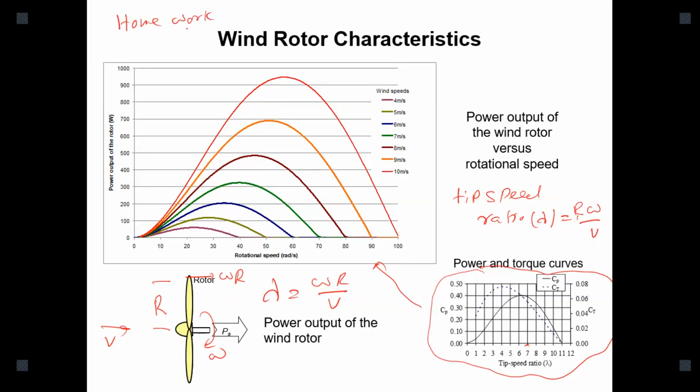Okay, I'll give that homework in the Moodle. However, for the homework, if you know the wind rotor diameter, shall we think our diameter is 126 meters, same as the Mana wind park Vestas wind turbine. If these are the CP values, and I hope this recording will upload, you take those CP values, then you can find out the curves for each and every wind speed. You can do that by using an Excel sheet.